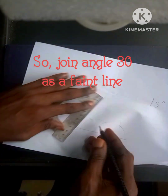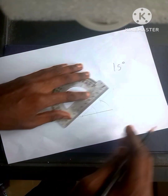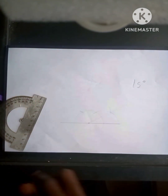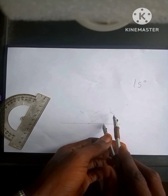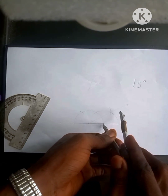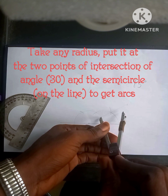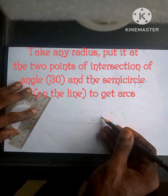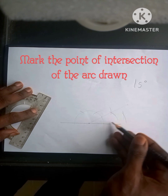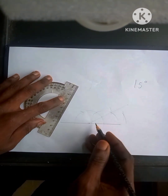What we firstly do, as a faint line, is join that line to that arc, so that we have a point to use as 30. That point of 30 to the first point will give us 15. So we bisect the two: put it at the first point, get an arc; put it at the second point, get an arc. Don't forget, any radius can be used there, but by the time you put it at those two points, you must use the same radius between them to get the arc.